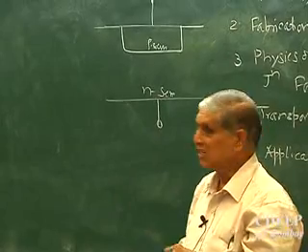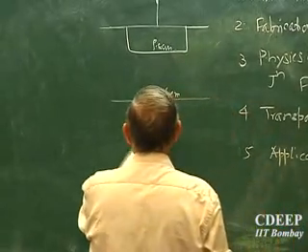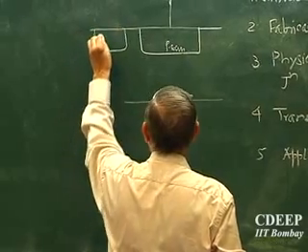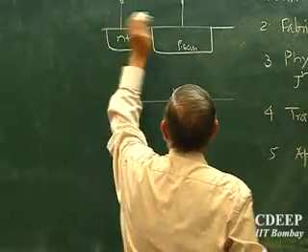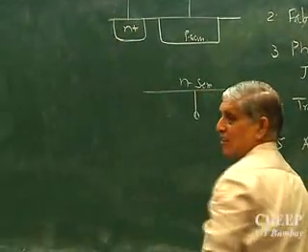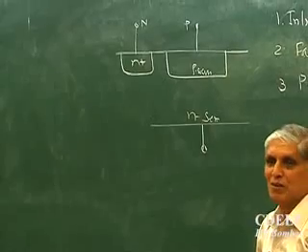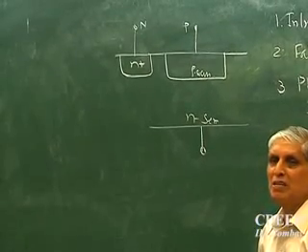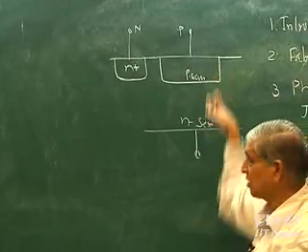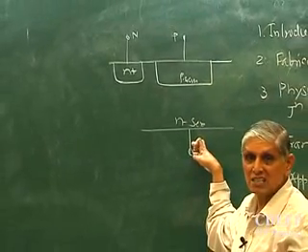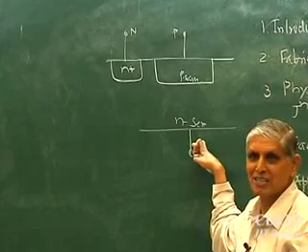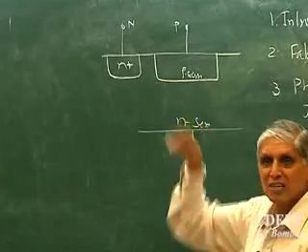Okay. And in some cases, I want both contacts on the surface, so I'll do another diffusion, we will see later someday. Then this can act like a PN junction. So both contacts are on the top. This is called a planar device. Every contact is on the top. Right now this is a vertical device. All integrated circuits do not use any back contacts. We can use them for some advantage, but not every time. Contacts are all on the surface.